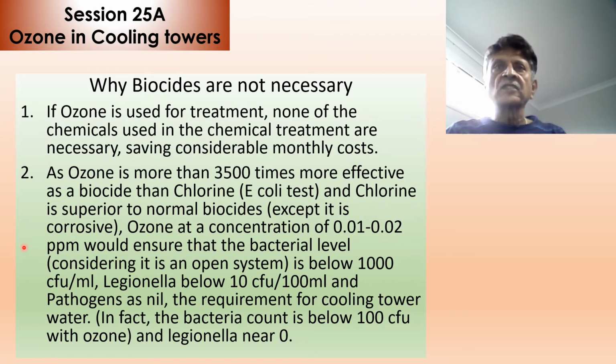Ozone at a concentration of 0.01 to 0.02 ppm would ensure that the bacterial level, considering it is an open system, is below 1000 CFU per mil, Legionella below 10 CFU per 100 mil, and pathogens as nil. The requirement for cooling tower water is the above.